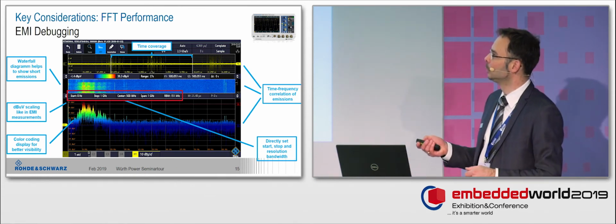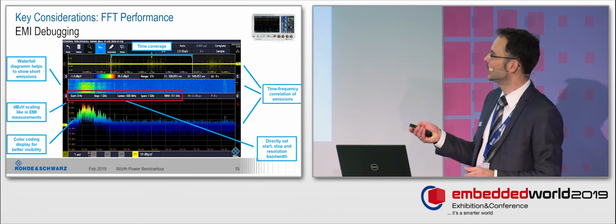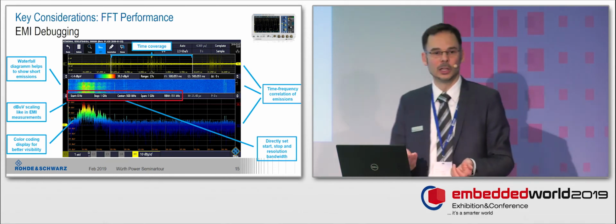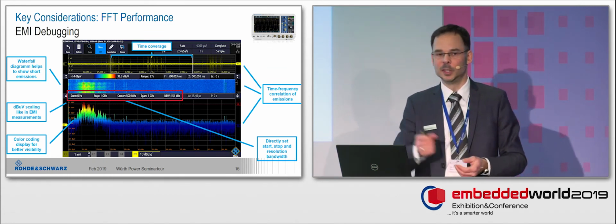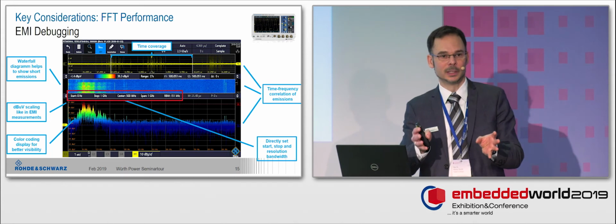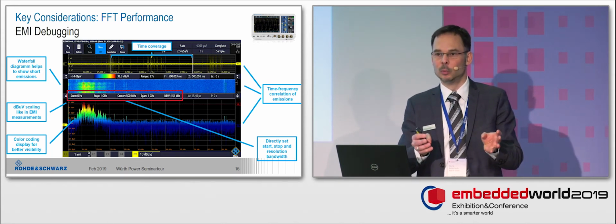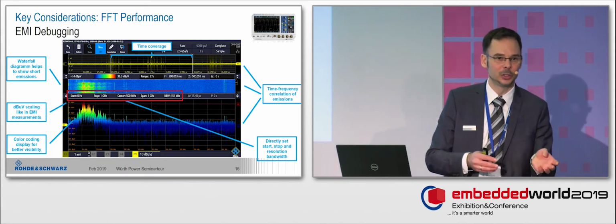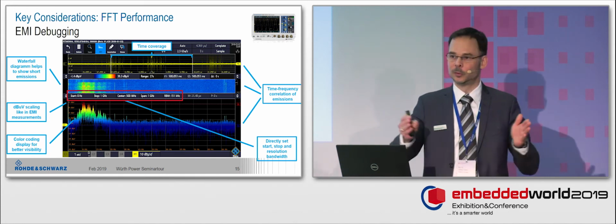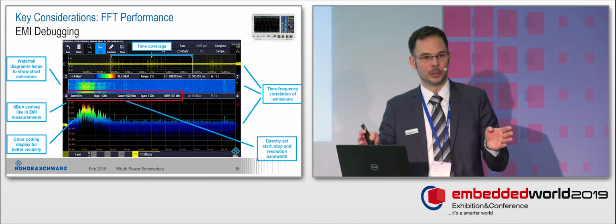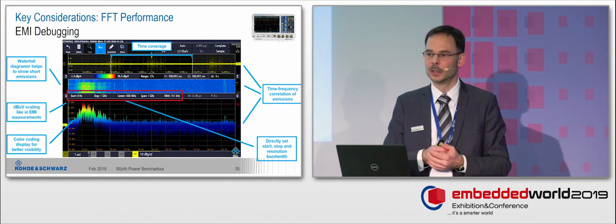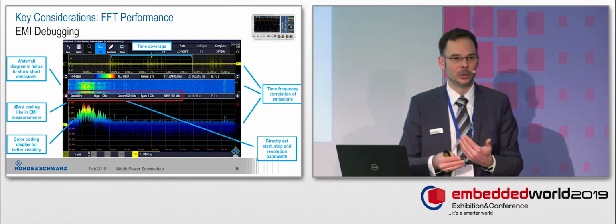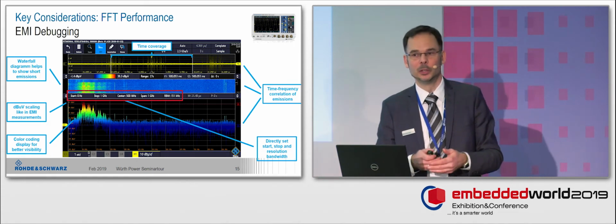What is important? The first thing is that you can control it in a sensible way. In the past, you had maybe an FFT button, and then you got a spectrum, and the spectrum depended on what FFT size you used and what time period you captured. So it was really difficult to navigate it in a way that you can use it. Today you can do it differently.